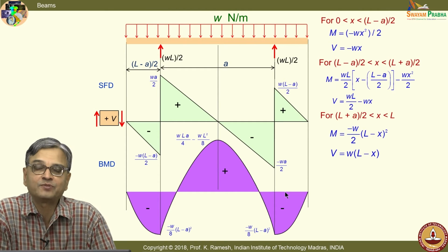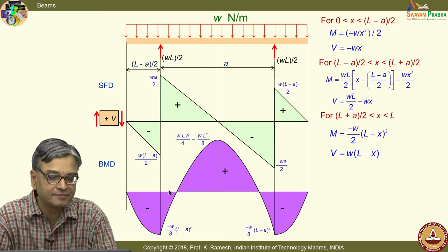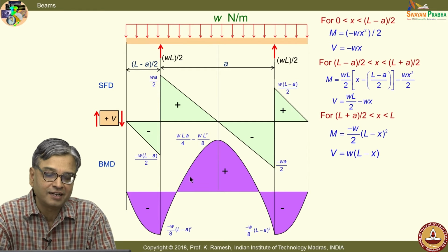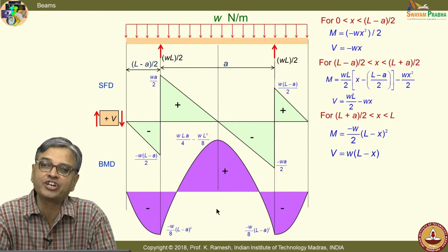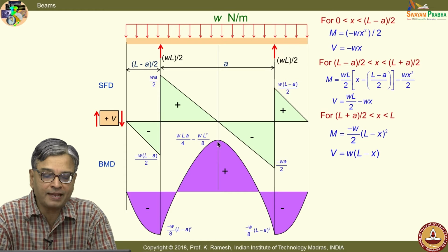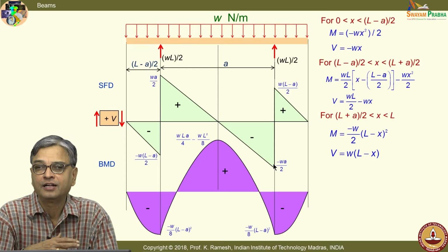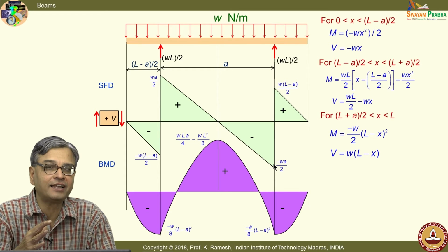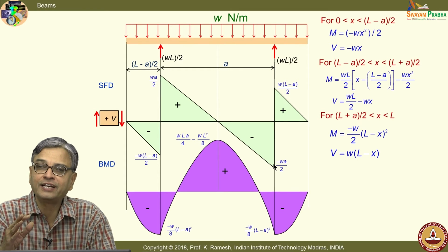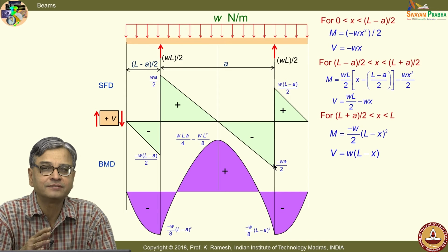The bending moment diagram is very colorful, and this is again illustrative. See, do not compare the peak magnitude of bending moment with the peak magnitude of shear force. They are shown very clearly to identify what the variations are. They are not plotted to a scale.